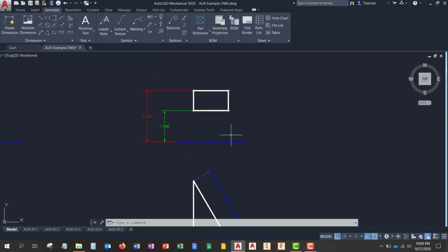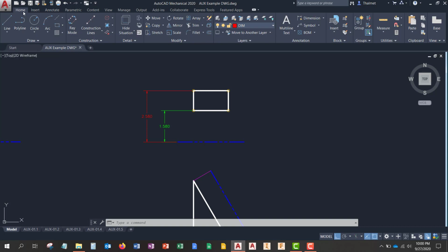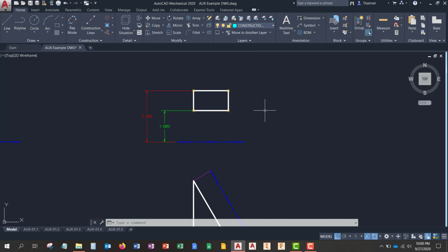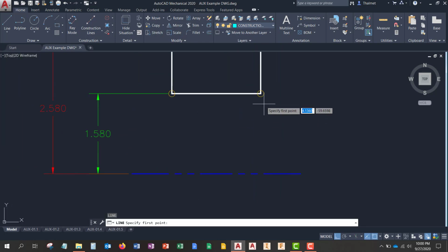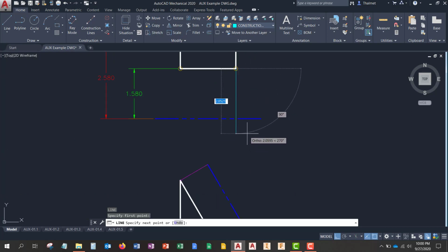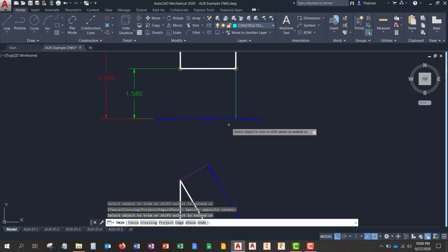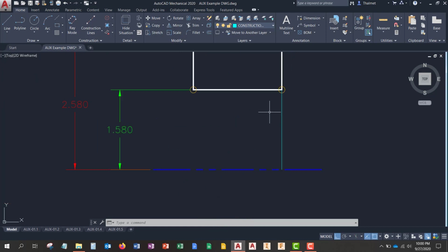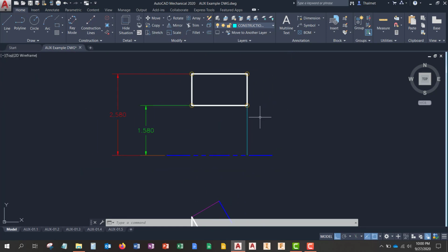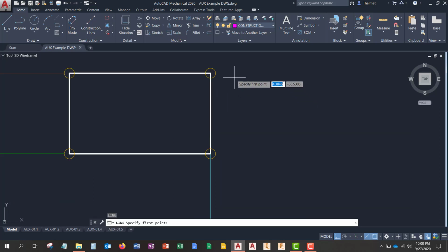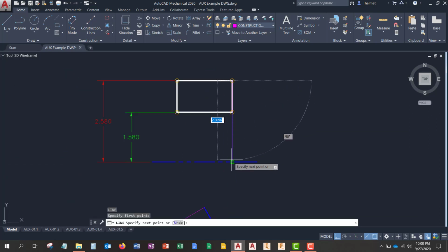Now, a somewhat easier method that I like to use is I'll just use construction lines. We can easily manipulate construction lines and rotate them around, copy them. So what I tend to do is I'll go to my point, draw a construction line down, trim it back to my fold line there, and then I have my distance without having to draw a dimension and then do a whole lot of extra work. So I'm going to do the same thing again for my point up here.